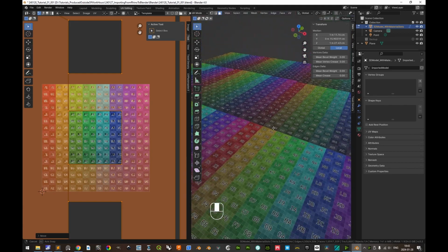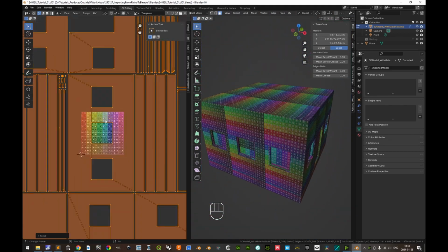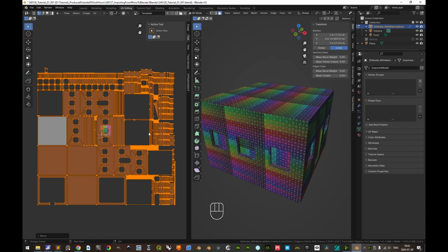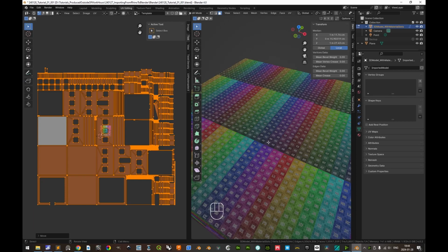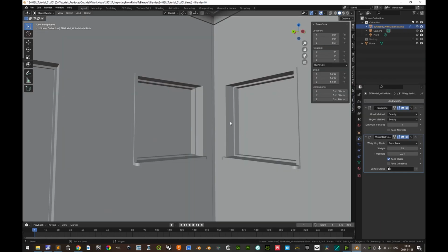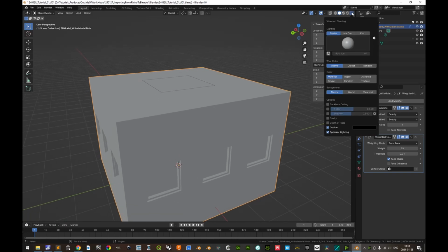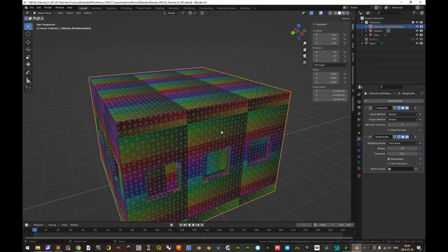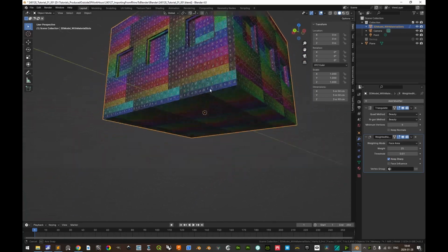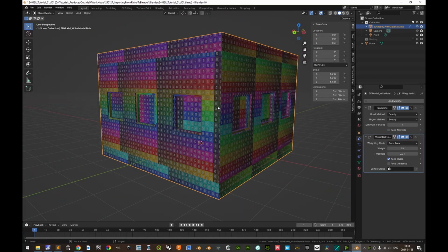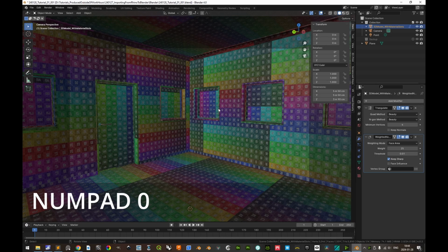That's good. All right. Now if we zoom out here in the UV editor, we see that all of the UV islands are approximately scaled so that the UV 0 to 1 space corresponds with a real-world reference dimension of 2 × 2 meters. We can go back to the layout workspace and see how everything looks. And here nothing has changed, of course. We need to change the color here to texture. Everything looks uniform enough.